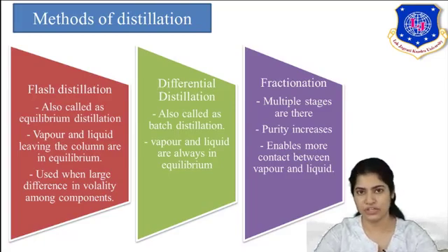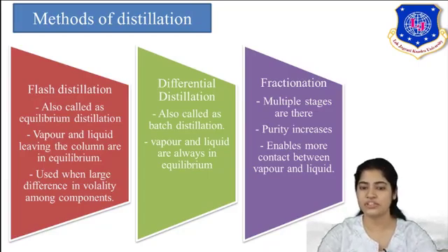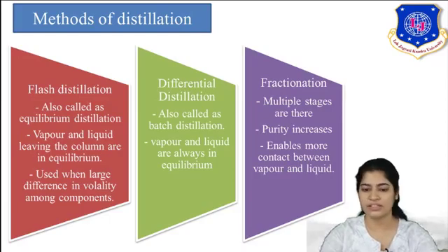The last one is fractionation. It is also called multiple stage distillation. In flash distillation and differential distillation, you can take the process as single stage distillation. But in fractionation multiple stages are there. Multiple plates are arranged in the column, and each plate behaves as a single stage.